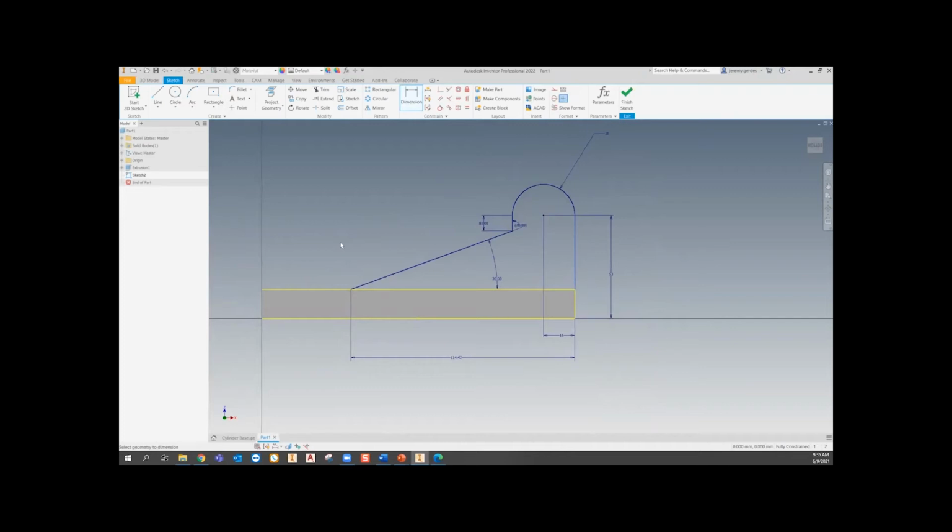We'll go more over dimensioning the sketch in a little bit with some easier examples, but I want to get the basics of just the sketching. And in the circles, you can do tangent circles, ellipses, and arcs, different ways, different types of rectangles. You can do your slots, you can do polygons, you can do fillets, you can add text, you can add points, trim, extend, offset lines. You can do patterns, some of your different constraints. Parallel constraints, tangents, perpendiculars.